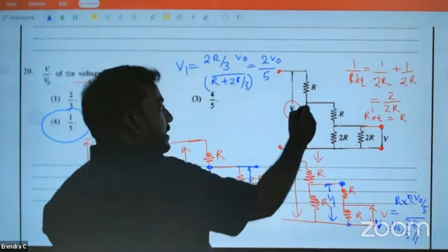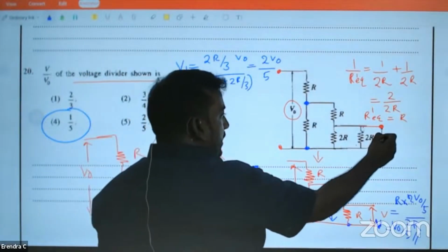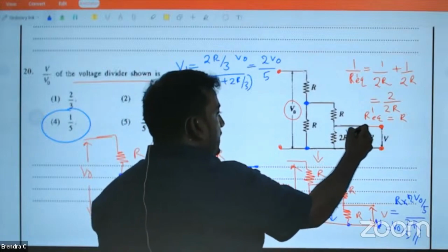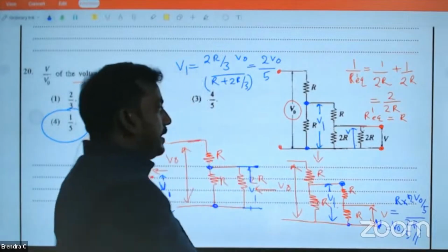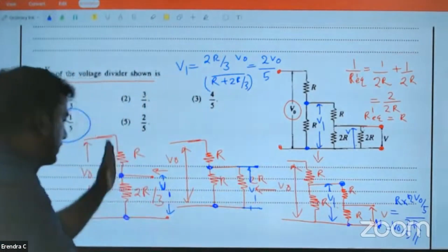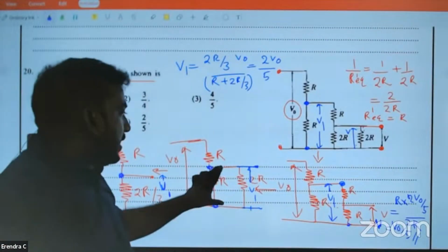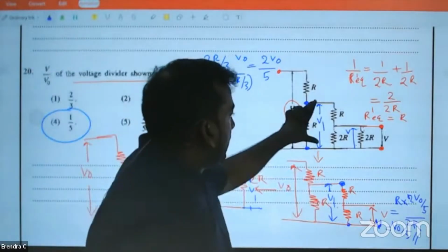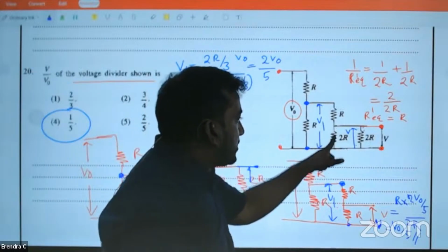So here, this voltage, this is V, this is also V. This voltage is V1. So what I did was you make the resistor circuit smaller to one branch. V1 I found. Once I know V1, here also V1. Voltage across this and voltage across there both are same.